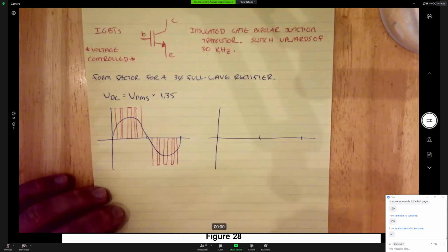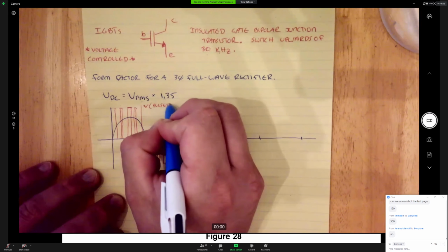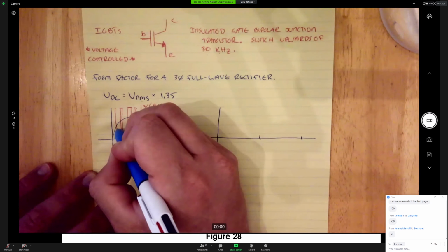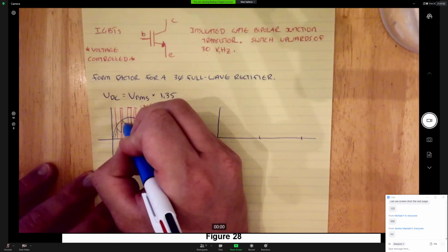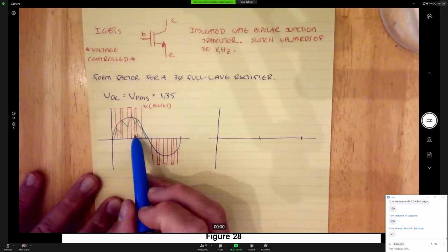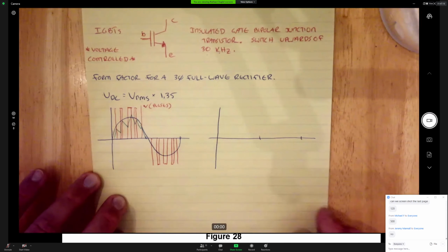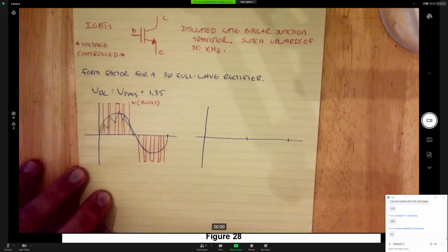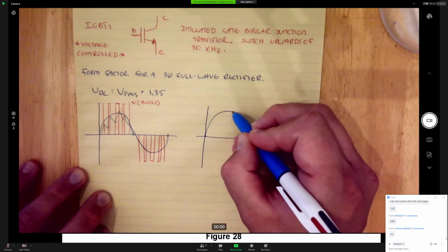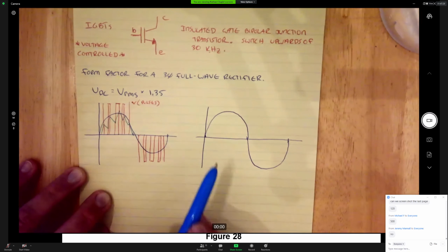So this is our voltage or our pulses, simulating the voltage. The current that gets drawn is going to go up and come down and go up and come down and up and down. And you guys can kind of see that jagged current waveform, not very good. So that will cause the motor to, again, generate more heat, possibly have some torque pulsations. But we can simulate this waveform here differently.